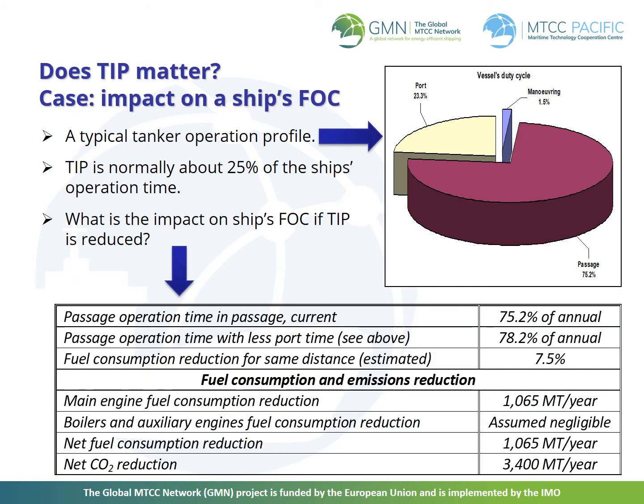The diagram shows the actual operation times for a specific ship, denoting that 23.3% of her time is spent in ports, combining berth and anchorage. The same ship was analyzed for a number of port calls and just-in-time operations, and the required time for just-in-time operation was estimated. If operated according to port just-in-time, the ship time in port will reduce from 23.3% to 16%, a reduction of about 30% of port time.